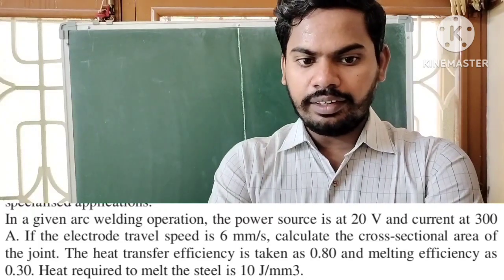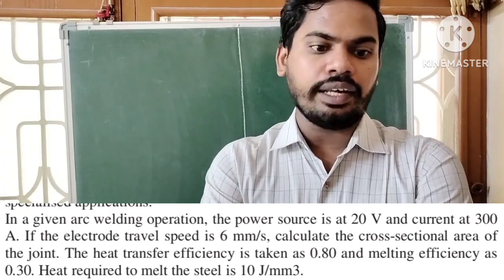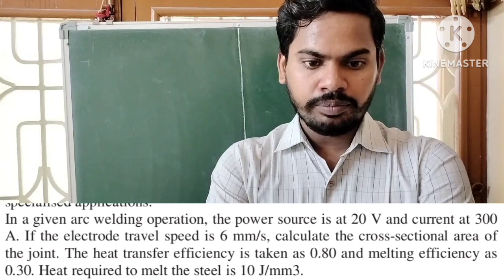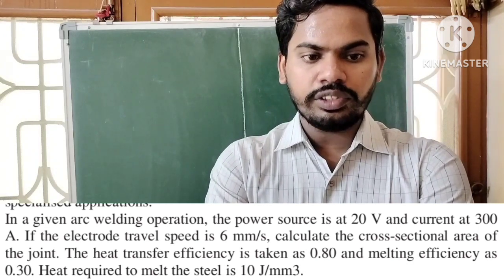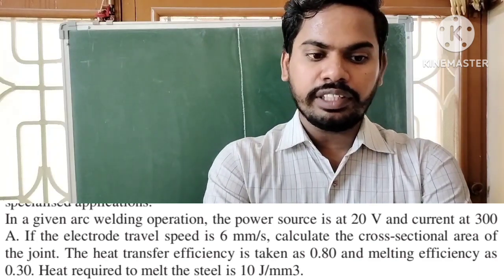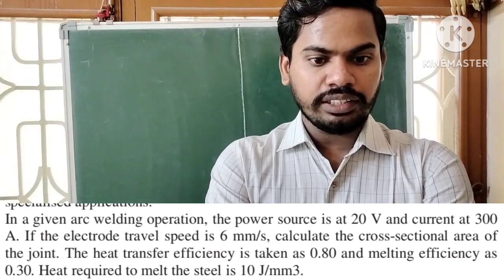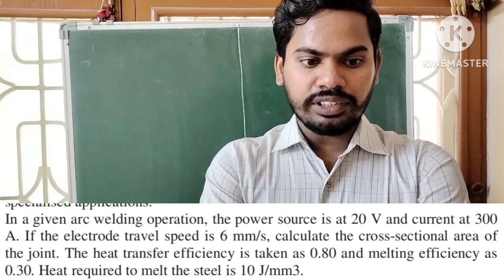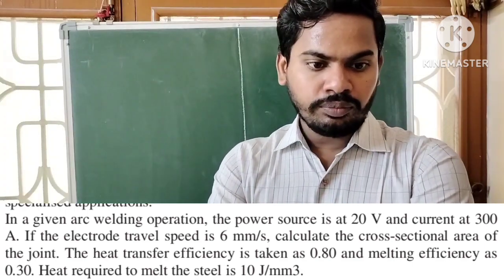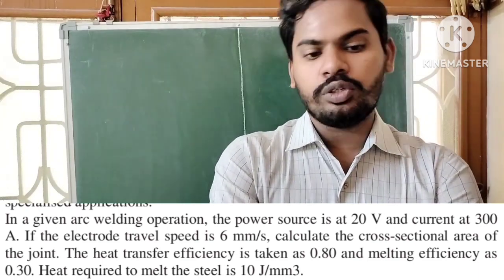In a given arc welding operation, the power source is at 20 volts and current at 300 amperes. If the electrode travel speed is 6 mm per second, calculate the cross-sectional area of the joint. So cross-sectional area of the joint means A, capital A. We have to find capital A. The heat transfer efficiency is taken as 0.80 and melting efficiency as 0.30. Heat required to melt the steel is 10 joules per mm cube.